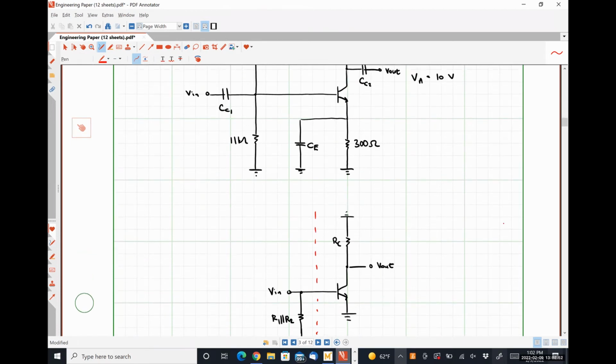So earlier I mentioned something about determining the small signal parameters, and then I got distracted, and we went off and talked about other things. So let's circle back around to calculating those small signal parameters. There are 3 for any BJT amplifier that we're going to deal with, right? Our transconductance gm, our resistance r pi, and our resistance r naught. So how do we calculate gm? Presumably you guys have been taking notes, look it up. IC over VT, absolutely right.